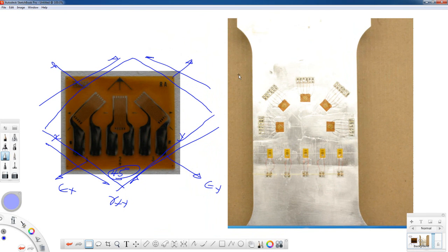And there's a weld right in the middle. It's called a plug weld. And we wanted to find out what was going on around the plug weld. These are stacked rosettes, so these three strain gauges lie on top of each other, and they're measuring the strains just like the rosette equations. And you see the solder terminals. Now these would go off to the instrumentation as different pairs of wires to measure that resistance.